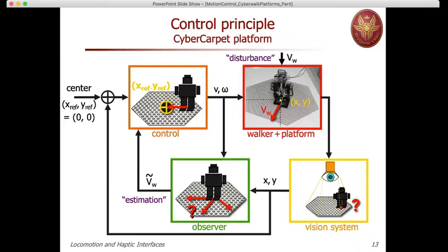And we will use this estimated intentional velocity, linear velocity, properly manipulated inside the control law, which will finally generate v and omega. So here again we have a part which is generated through a feedback of the error, and a part which is generated as a feed forward intended to compensate the unknown disturbance. So this is the overall picture.